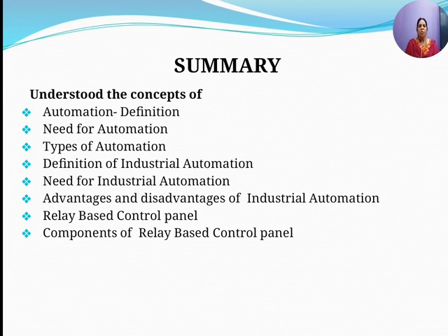So the controls for a small system consist of a relay logic panel. A relay is a simple device that uses a magnetic field to control a switch. When voltage is applied to a relay coil, the resulting current creates a magnetic field. The magnetic field pulls the metal switch towards it, thereby closing the switch. The contact that closes when the coil is energized is called normally open, and the normally closed contact opens when the input coil is energized. Relays are used to let one power source close a switch from another power source.